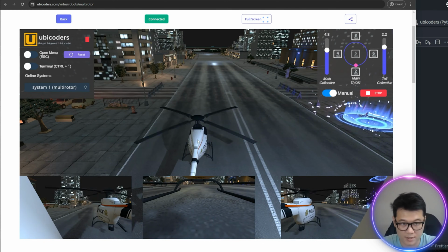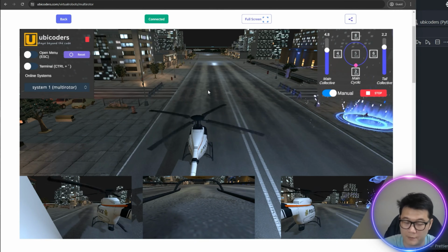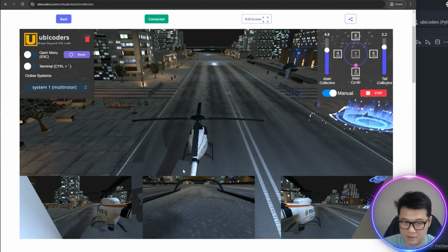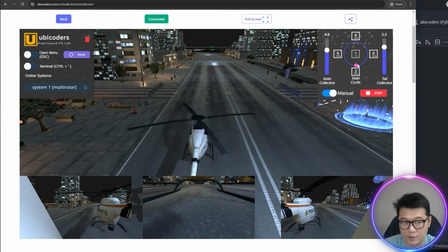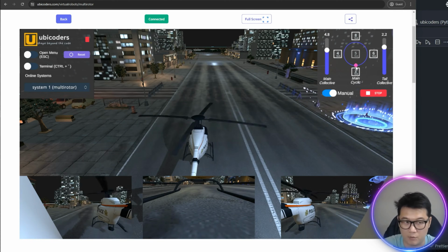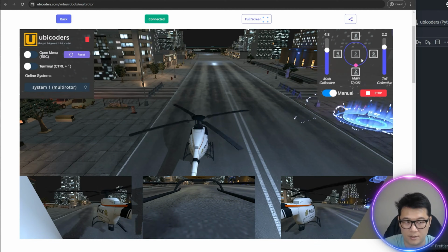And then towards the right side is 90, 180 is the front of the helicopter, and then 270 degrees, just defined as a traditional helicopter azimuth angle definition. And then the amount of the pitch angle for this cyclic motion is defined by the distance between the center and here. So that's how you want to control the cyclic motion.